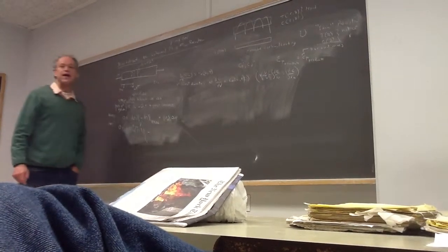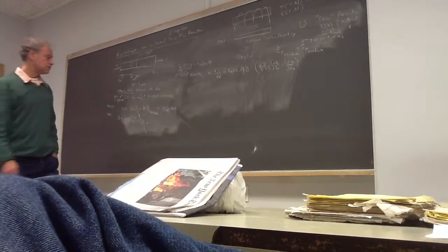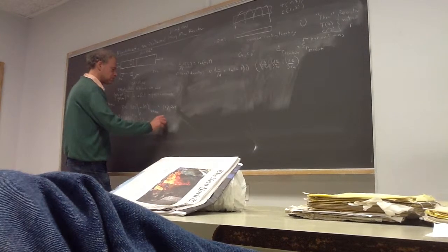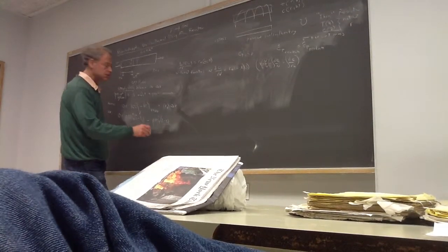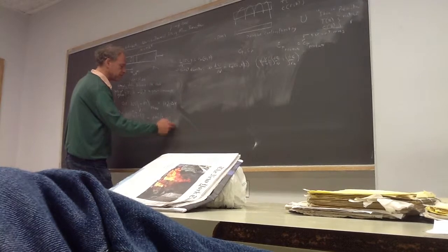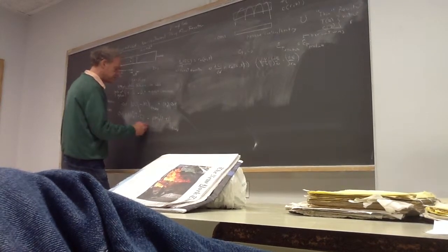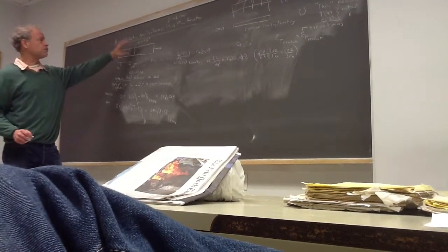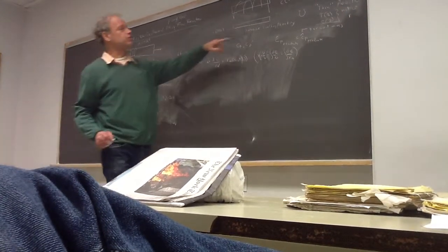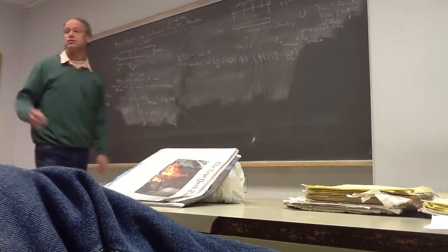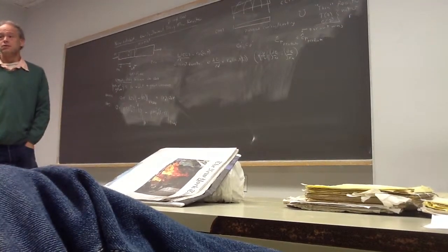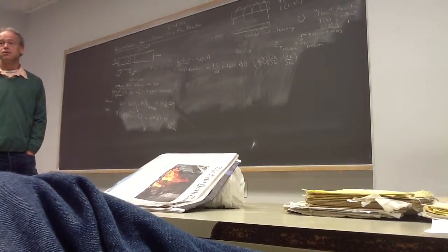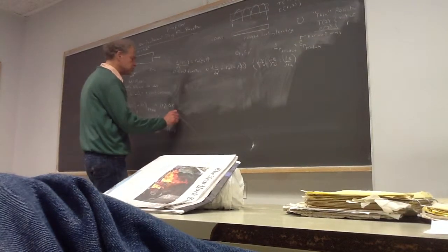What is out? The density times V times CP, T minus T naught at Z plus delta Z. Here I'm doing a V plus delta V. If I have passive cooling, then I also have cooling by virtue of U. It's like the Q, so it's minus U. U is the heat transfer coefficient.